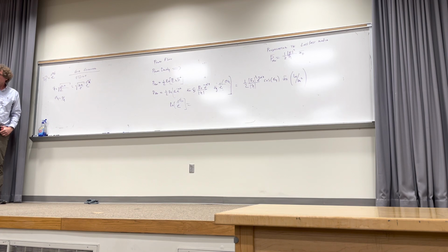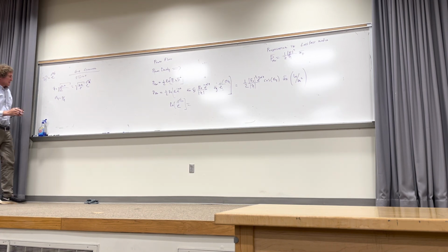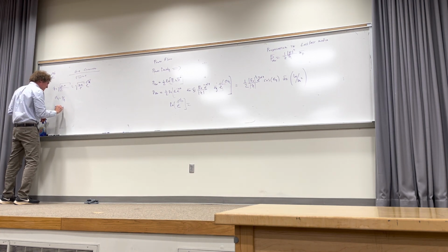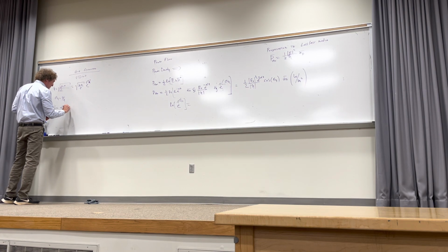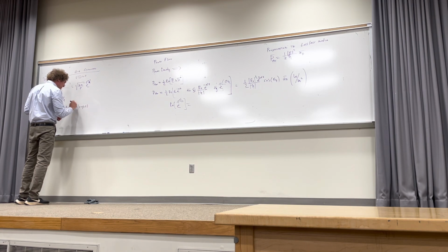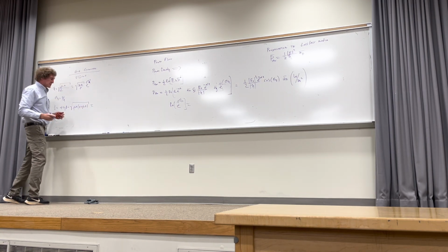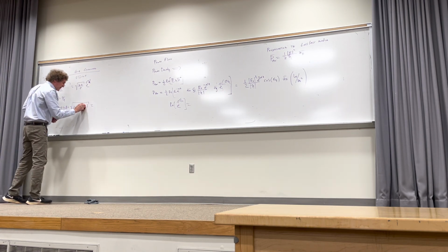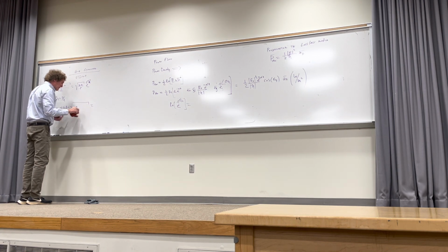Correct, class? All right. Now, if we've got that, the next thing we need is gamma, or the propagation constant, which is alpha plus j beta. Remember, that's equal to the square root of j omega mu times sigma plus j omega epsilon. And if it's a good conductor, what do I do again? That's right, this goes away, and I have just sigma here, right?